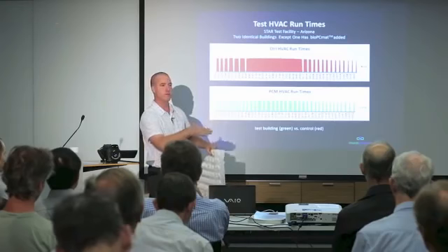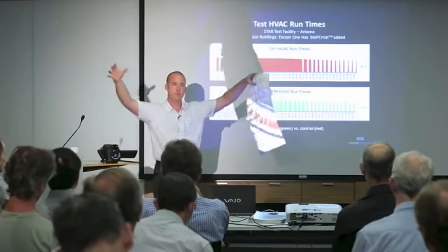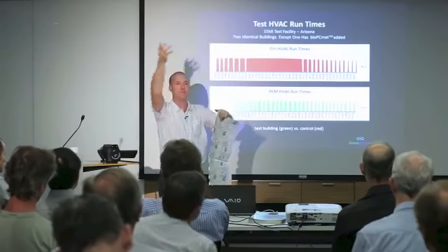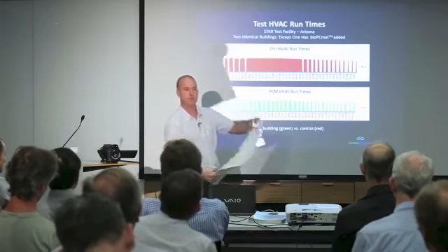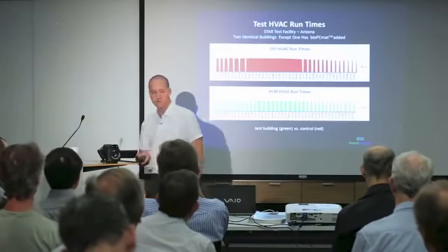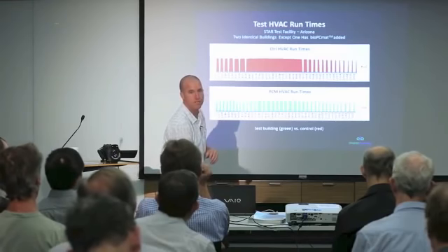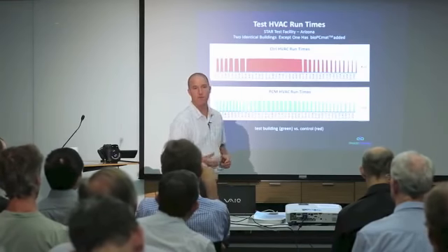So they could pre-freeze it before everyone got into the restaurant, and then when everyone arrived, the heat would gush up to the roof, pass past the curtain on the way to the aircon return, and be pre-cooled. So the aircon worked a lot better, and obviously saved them a lot of money too. So a really good way to use phase change material is to help an air conditioner, an old one, work much better, or a bad one work a lot better.